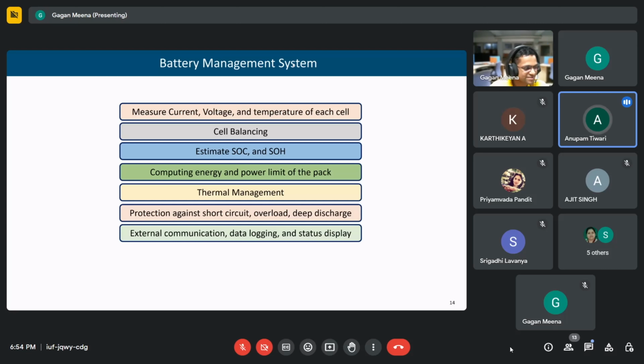So that means every vehicle which is electrified, the EV battery, is lithium-ion only, not nickel cadmium. Right now we have all lithium-ion, and for these three-wheelers, these e-rickshaws, they use lead acid batteries. Why are they not using lithium-ion? Because of cost. The main reason is cost. And they use BLDC motors. So both of these are used to reduce the cost. And these four-wheelers don't use BLDC motors, they use PMSM, permanent magnet synchronous motors, or some of them also use induction motors.